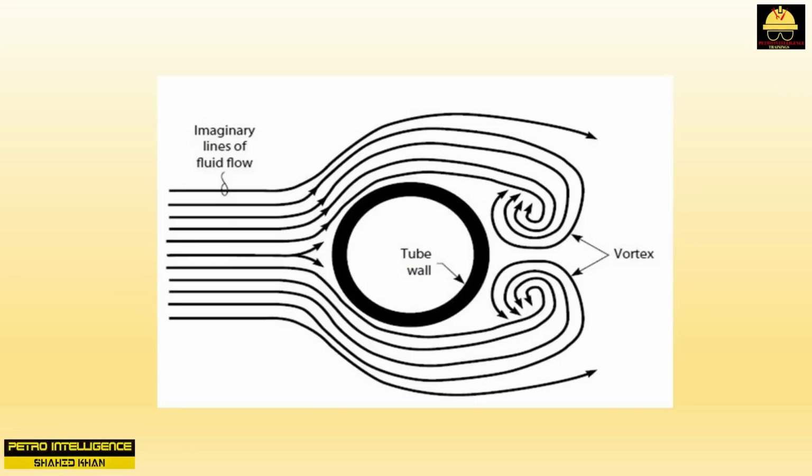The best way to diminish the effect of laminar flow is to place the higher viscosity fluid on the shell side. The shell side of an exchanger is far more resistant to heat transfer loss due to film resistance than is the tube side, because of the vortex shedding shown in the picture, the rapid changes in direction due to the tube support baffles. Purely in terms of heat transfer, it follows that the higher viscosity fluid should be placed on the shell side. Sometimes, pressure and corrosion force the designer to allocate the higher viscosity fluid to the tube side. Also, your maintenance department would vastly prefer that the fouling fluid be placed on the tube side.